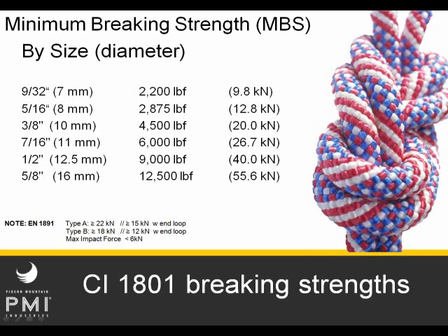You'll also note on the left-hand side column an inch reference using English units. So you can see the correlation between millimeters and inches. That's an important thing to notice, that these are not precise. Actually, half inch actually comes out to 12.7 or so. So it's not exactly precise on the scientific measurements, but it's what we tend to call things in the industry, and so we've drawn some correlations there as well.